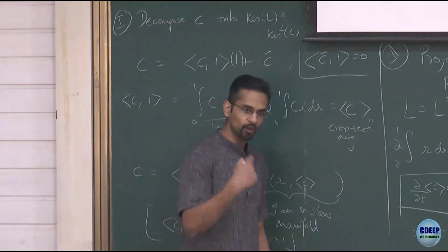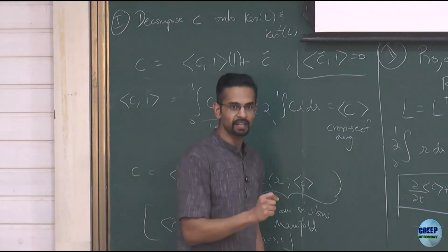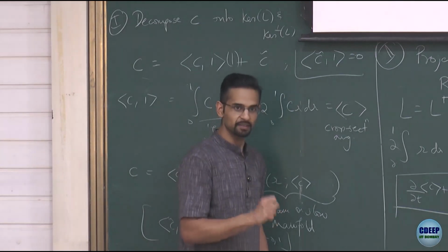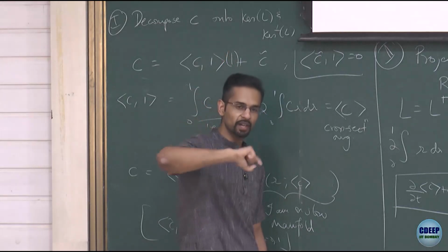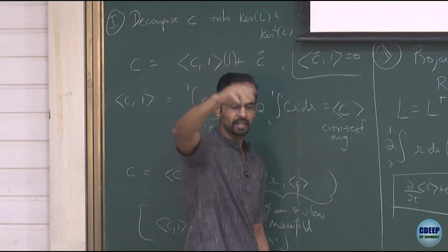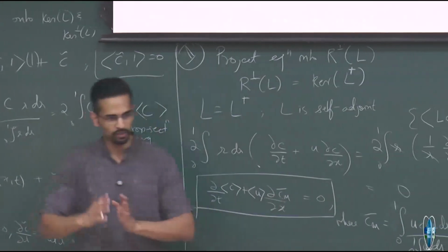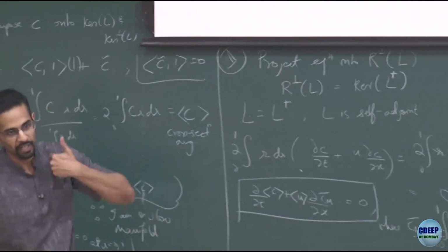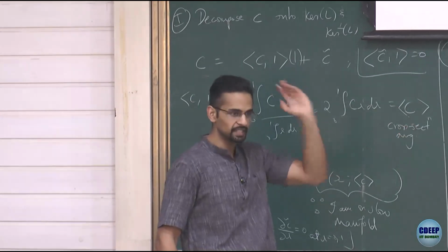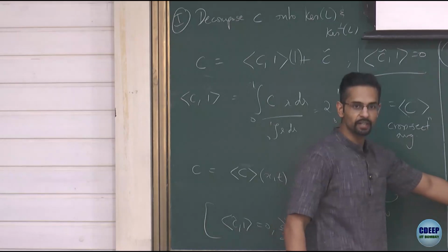So the fact, no matter how small, that there is this finite radial direction gives you an effect because you are waiting for infinite time. So no matter how small the difference of time scale is, you are waiting for an infinite time. And that build-up gives you some difference, and that difference is what's going to account for this spread. If you say, no, I have very fast radial mixing, so I'll just assume that the concentration is uniform, equal to the cross-section average, you'll get a completely qualitatively wrong result.